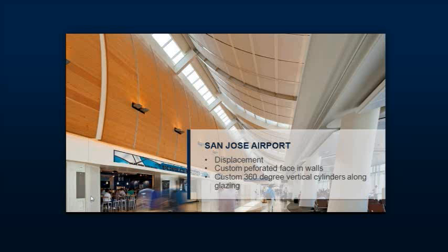And then along the exterior where all the glazing is, there are these vertical units originally installed, cylinders with a domed top on them. And we're supplying from two sides in this case because it is a fairly wide space. The typical surface area distance, our design goal, is 30 feet as a radius. So I mean, this is very well handled. Again, a very comfortable place. And we've seen a lot of airports worldwide start using or have been using displacement ventilation.